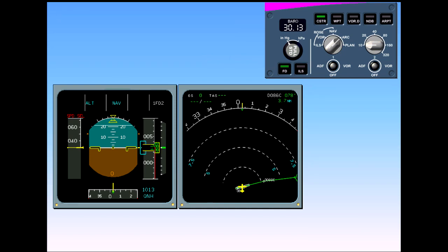Notice that there are no Flight Director crossbars displayed. This is normal because on the ground they are not required. You will see later that during the takeoff, the Flight Director command bars will automatically appear. You will learn more on flight directors in the Autoflight modules.